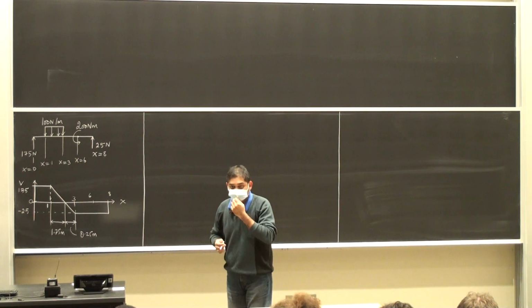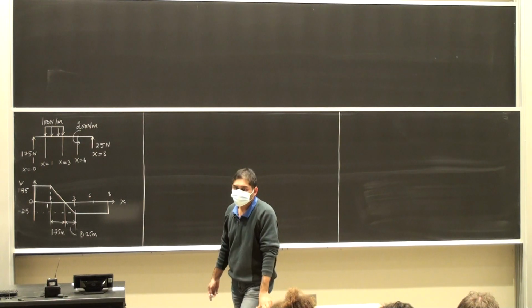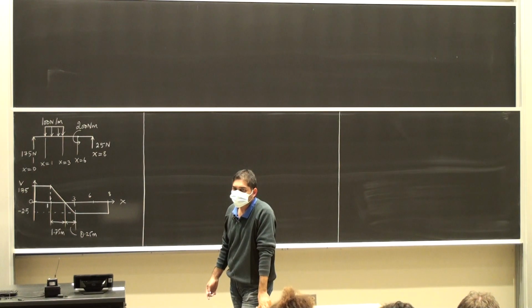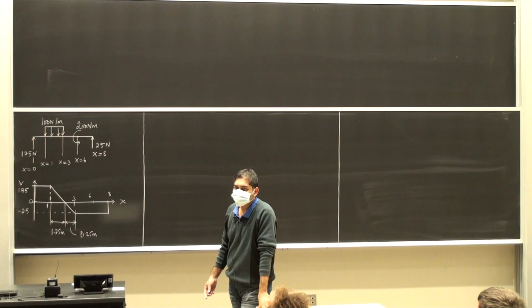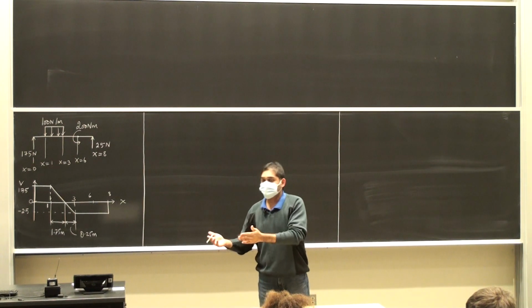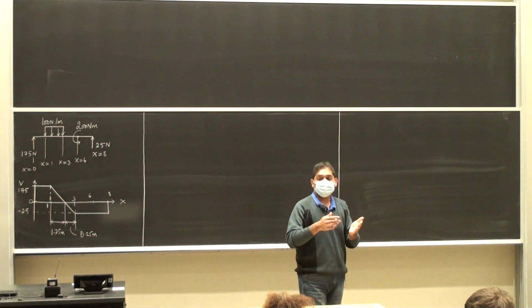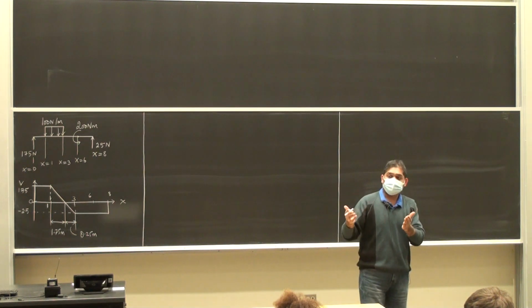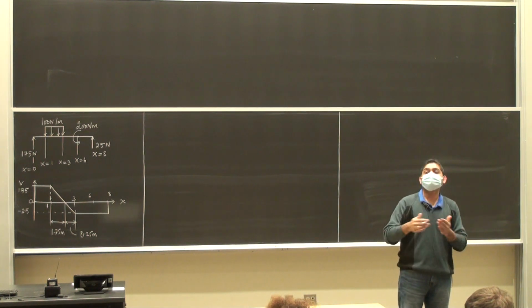Okay? All right. So when you're drawing the bending moment diagram, you need... Okay, your question. So although we've taken a look at linear and quadratic lines, are we also going to look at cubic? It can be anything, right? If the slope is a linear slope, the curve is going to be a quadratic. If the slope is a constant, the curve is going to be a linear.